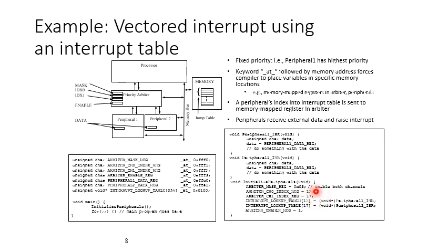Channel 0 will have its ISR at 13, whereas channel 1 has its ISR at 17. So you can see here interrupt lookup table 13 for channel 0 and interrupt lookup table 17 for channel 1. These are all the assignments.